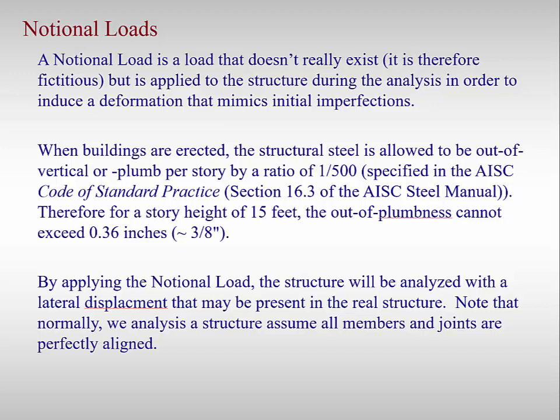Now, notional loads are loads that really don't exist. But basically what happens is we apply these notional loads to the structure that will push the structure over a little bit such that it'll begin to mimic the imperfections that we normally have in columns.